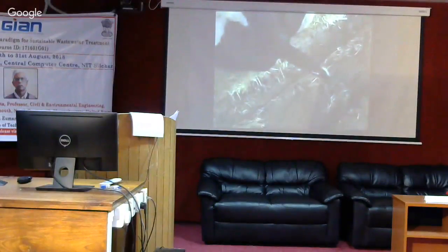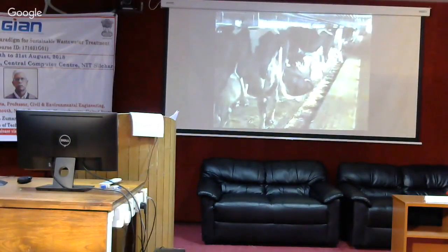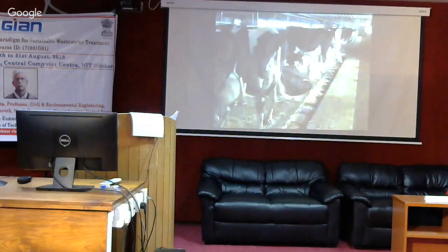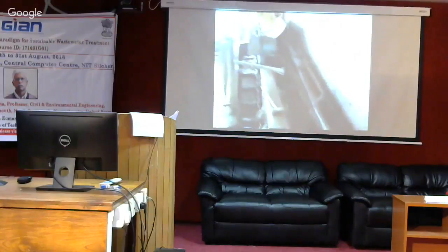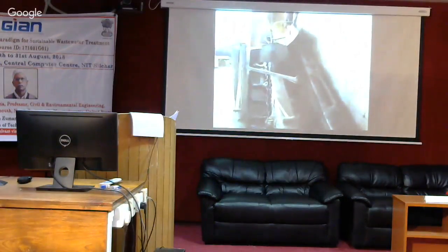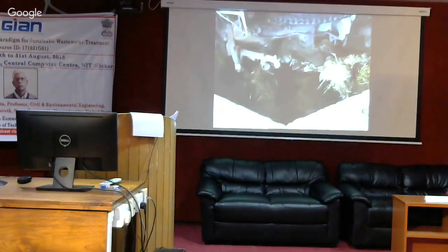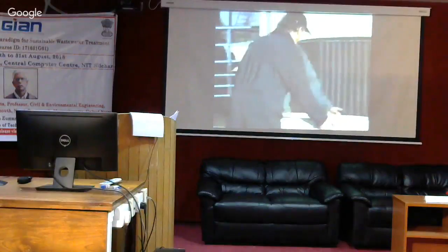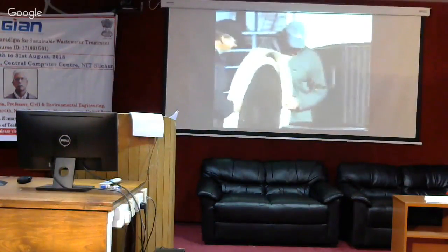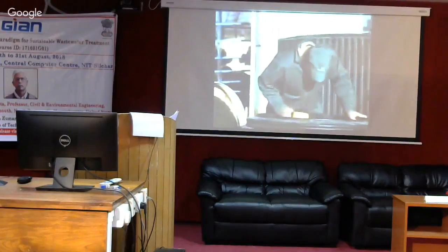The manure comes out from the cow, goes into the gutter. We run the gutter twice a day, morning and night. The manure goes all around behind the cow. It comes up here. This incline goes down in a 3-foot pipe. There's no pump, it's gravity fed, and runs out to the digester. The manure is stored for 28 days in the digester.